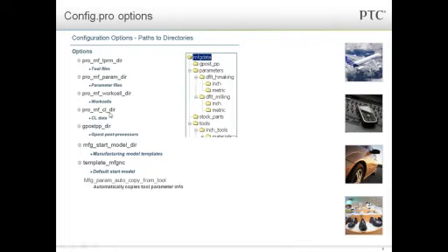The next option you see right here is you can actually tell the software if you want it to always put all of your outputted CL, your NCL or CL data files and post-processor your actual G code into a specific folder if you want it to, and essentially that's what that config option does. So it condenses where all of your toolpaths are all over the place, and in different folders you could drag them into a specific spot or have it automatically go into a specific spot if you'd like.